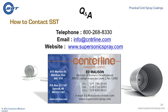We've got a customer right now who's successfully applying a very thin coating of tin over copper as a replacement for tin plating. And most of our customers know that plating is a very slow process that applies very thin metallic coatings to other substrates, but it's very uniform and it's got some very, very good properties. That customer that I mentioned earlier is applying 30 microns with a nice, continuous, consistent coating. So I would say that's pretty well our lower limit mark, around that 30 micron, just over a mil coating thickness. Okay, great, thank you.